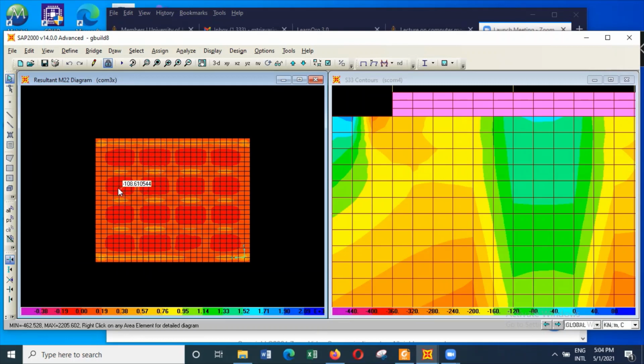are cellular raft. So in the cellular raft, we get a bending moment of 126, and some places we get 111, 130, and 120. And here I saw 140 somewhere, say 130. And the thickness of the slab is only 450 millimeters.